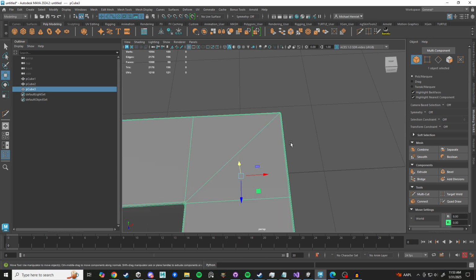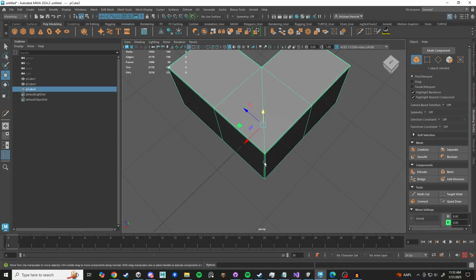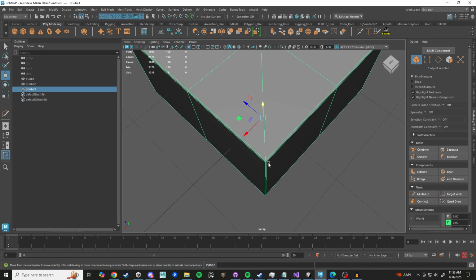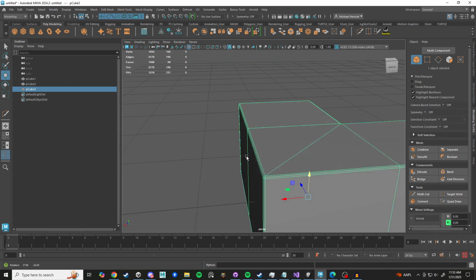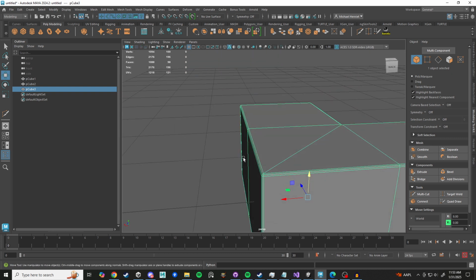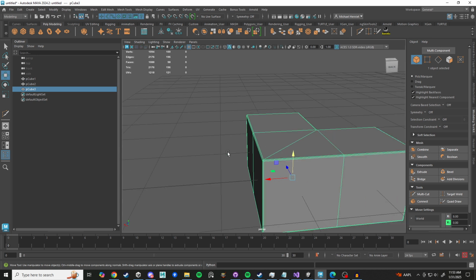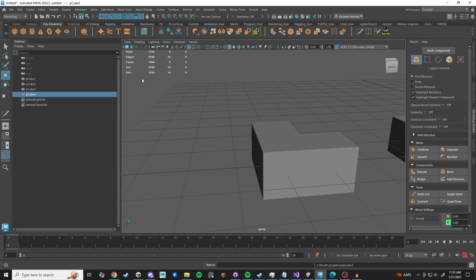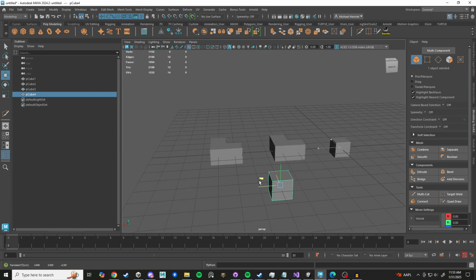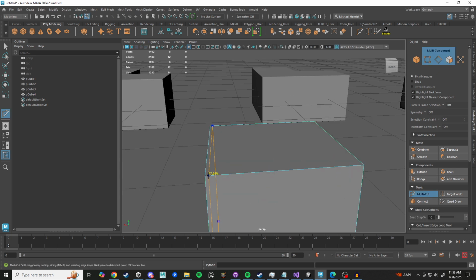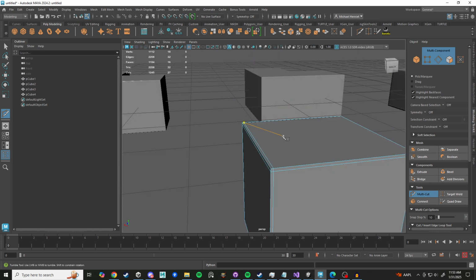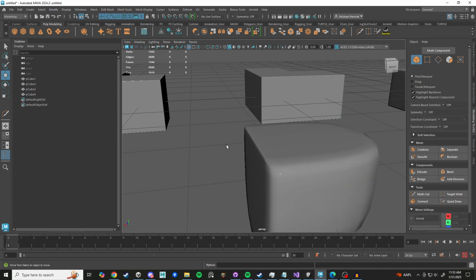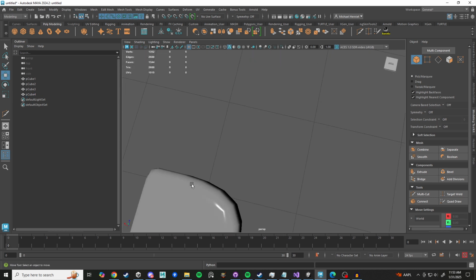And then you have completely quadded out geometry, right? And then note that you have that singular edge that then splits. So then these 3 edges are retaining that shape. Whenever you're beveling, you want to do 3 edges. And if you want a flat surface, you have to understand, let's get a new cube here. You have to understand that you need multiple edges to retain a true flat shape there, right? So that's why I do the 2 edges there.